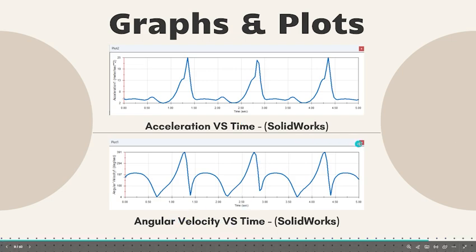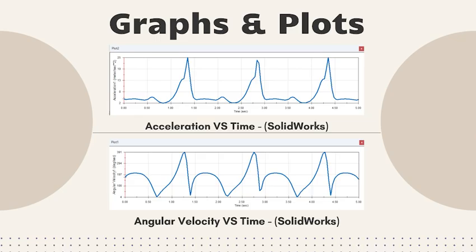So what does it actually show? This plot shows that even though our motor runs at a constant RPM, the output link of the mechanism does not move uniformly. The waveform reveals how the linkage geometry naturally speeds up and slows down at specific angles. This is exactly what we want in a wiper mechanism: smooth sweeping in the middle and controlled slowdown near the reversal points. It proves that the mechanism converts constant input motion into functionally useful non-linear output.